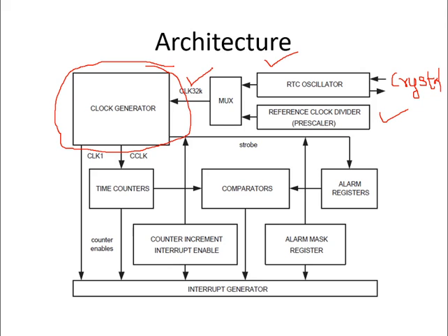One way it is described is as a 2 raised to 15 counter. A binary counter is going to generate this clock signal, and it gives you a round figure there. That means when its MSB is high, exactly 32.768 kilohertz is generated. That is one explanation of that frequency.